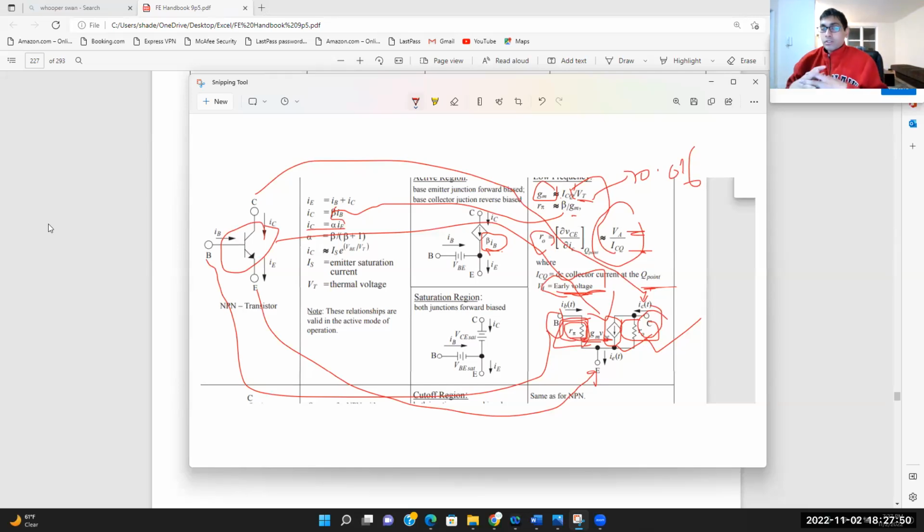So as I said, to summarize, small signal analysis is nothing but, if you have an AC signal applied to a transistor, it's not as straightforward as when you only have a DC signal. Your BJT needs to be replaced by a hybrid pi model, the one over here.